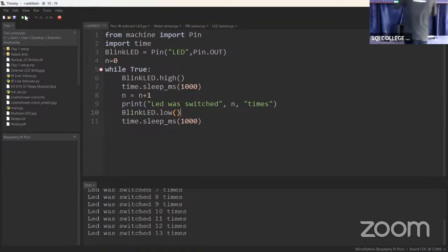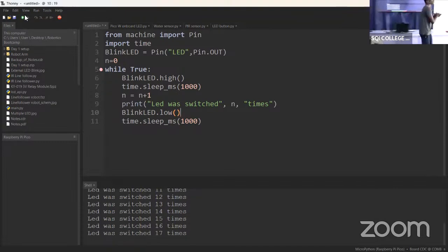Yeah, so you see this, I call it serial monitor. It helps you to understand what is going on in your Pico currently before you actually deploy your programs fully. So you know the state of all your sensors, you know the state of all your pins before you finalize anything. That way you can monitor the variables and every other report. So I ran a string, I put the value of n, and I ran another string.